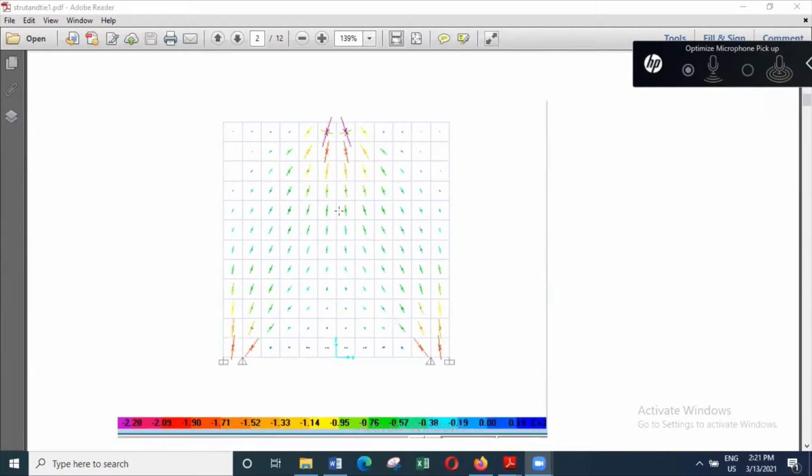If you look at this, this is a result of the FEM model, and what you see is, the load that is applied here is gradually transferred in this direction, and the loads on this side are transferred here. In addition, you can see some blue color lines, and blue color lines correspond to tension. So at the bottom of the wall, you get tension, and all these loads are transferred to the supports using the compressive strength of concrete.